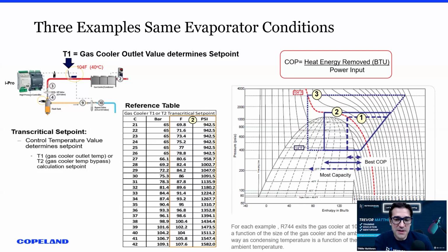Yeah, and I learned something yesterday about the enthalpy diagram. Those dotted lines inside the bell curve, we know that's two phases, but the dotted lines that go up are flash gas percentage. As you push that, because you always want to go as far left as possible, that means you've got less flash gas, you've got more liquid.